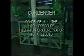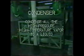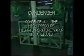The condenser must be able to do 2 things. The condenser must quickly condense all the high-pressure, high-temperature vapor to a liquid, and it must be able to provide a continuous supply of subcooled liquid to the metering device at the evaporator inlet.